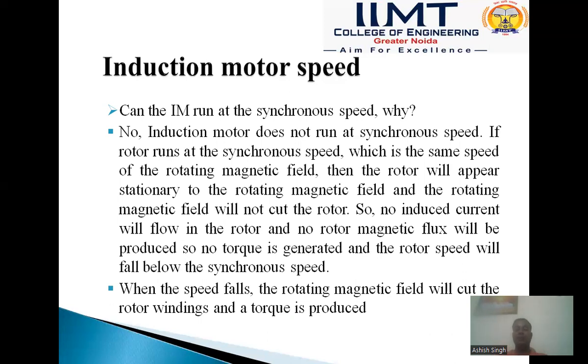And since there will be no flux produced by the rotor, the net torque produced by the induction motor will become zero. So, a three-phase induction motor cannot run at synchronous speed. When the speed falls, the rotating magnetic field will cut the rotor winding and torque is produced.